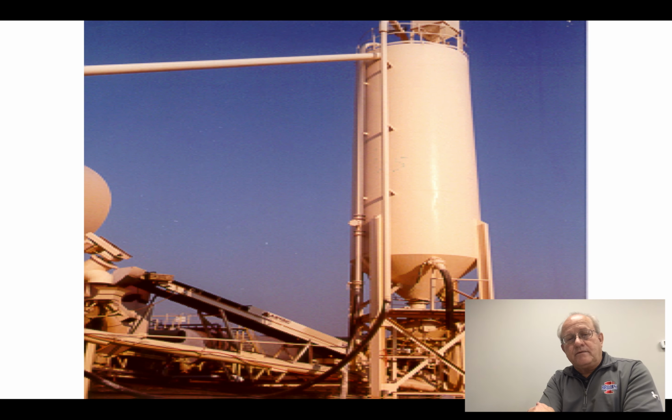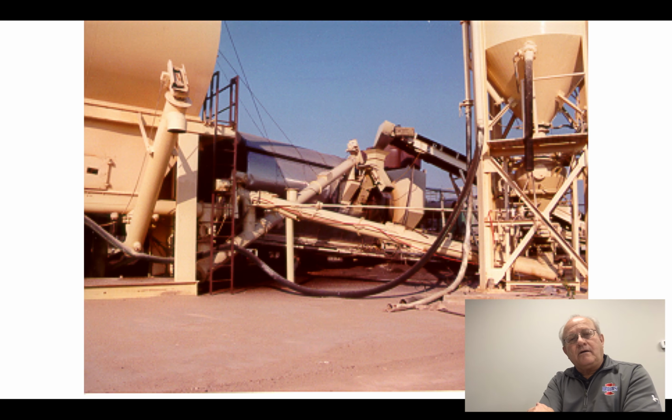Dust silo. So all the dust comes out the bottom of the bag house. It's augured or blown into these dust silos. And then at the bottom of them is a rotary airlock where you just meter back in what you need. All the conveyors move the dust. There's one there coming out, doesn't have anything on it. That's in case you need to empty the bag house or you need to waste it.